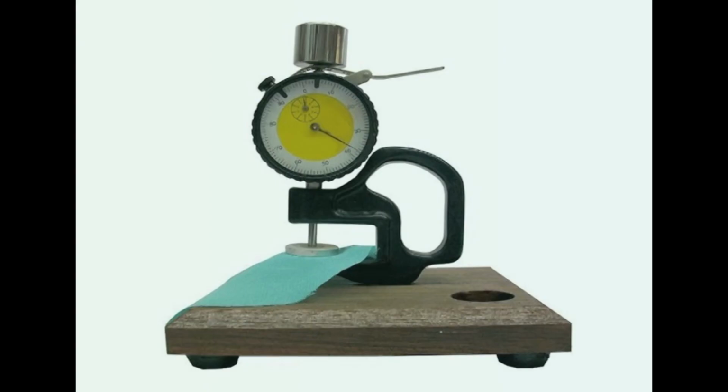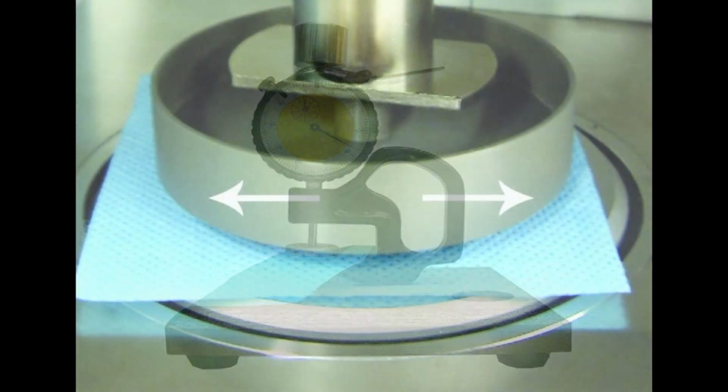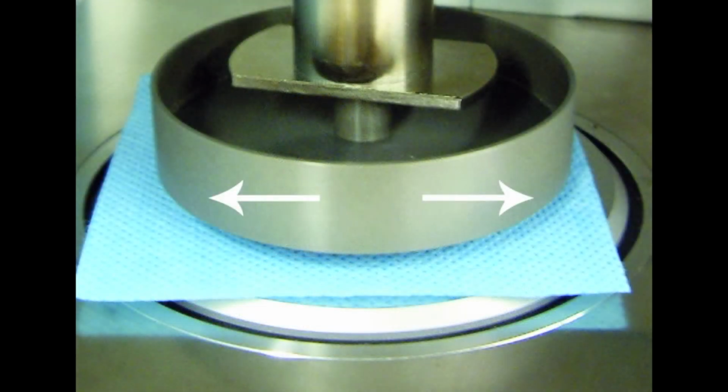The principle of measuring thickness is expressed neatly in BS 2544 of 1954. Essentially, the determination of the thickness of a compressible material such as textile fabric consists of a precise measurement of the distance between two plain parallel plates when they are separated by the cloth, a known arbitrary pressure between the plates being applied and mentioned. It is convenient to regard one of the plates as the pressure foot and the other as the anvil.